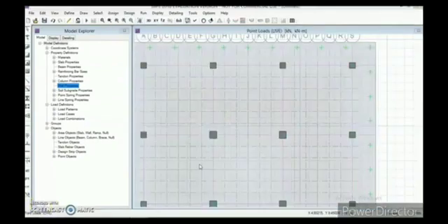In the meantime I have assigned the remaining dead loads and live loads to all the 16 columns. So now the assigning part is done. We have actually assigned the loads to it as well as the concrete properties initially, and before assigning the load properties, we have also assigned the steel properties to the column. We have already assigned the soil properties to the footing as well. So now everything is done. We just need to check our analysis.